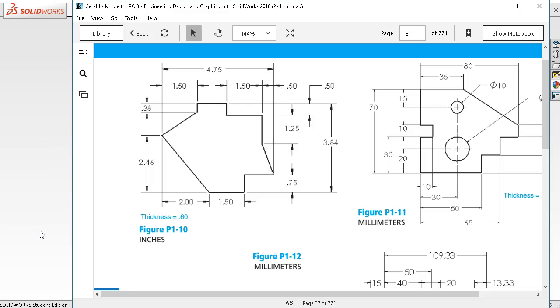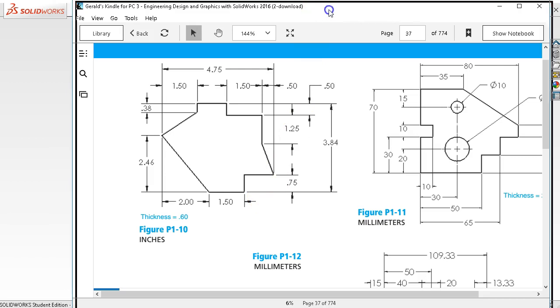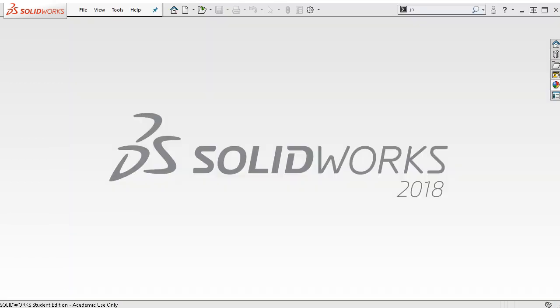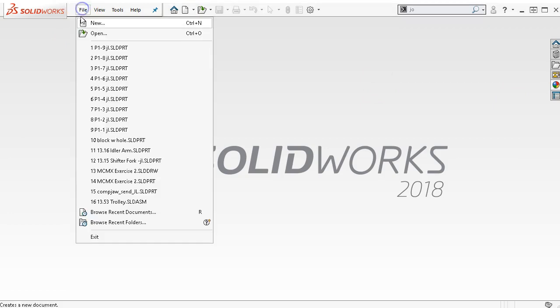Looking at this part, we have lots of angles, lots of geometry, and the issue here is that we're going to start to infer relations that we may not have really encountered up to this point. As we build out this geometry, whichever way, clockwise or counterclockwise, this line is going to want to be parallel or perpendicular or coincident to something over here. We're really going to have to pay attention to those relations. This one might be a good one. I'll give you the option to do it as a contour and region. That would be a good strategy.